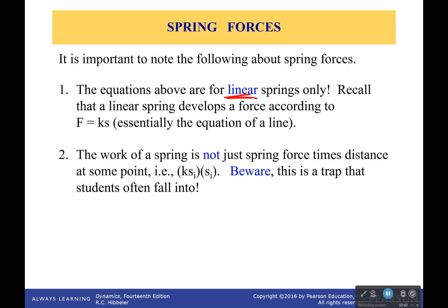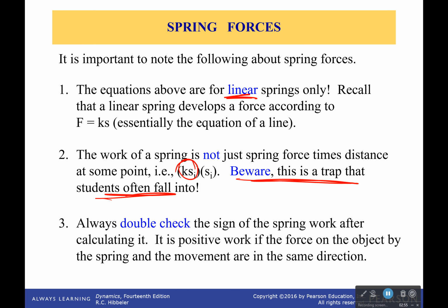Second, the work of a spring is not just spring force times distance, because the spring force changes with position. This is something that happens to most students. They make this mistake at some point, so don't let that be you. And finally, third, always double check the sign of the spring work after calculating it.